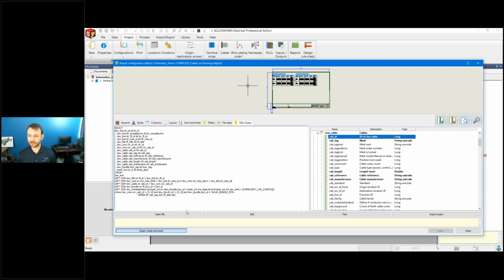Especially if your tags or your file IDs get into the double digits, and you don't have leading zeros, you'll see 1, and then 10, and then 11, 12, and then it'll fall back down to 2, 3, 4. So it doesn't follow the ASCII sort order. That's what this ASC is telling it to do, to follow that ASCII sort order. So that way it shows 1, 2, 3, 4, 5, 6, 7, 8, 9, 10, 11, 12, versus 1, 11, or 1, 10, 11, that information, okay?